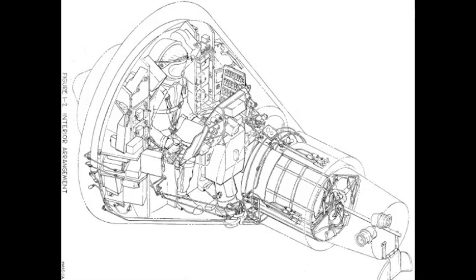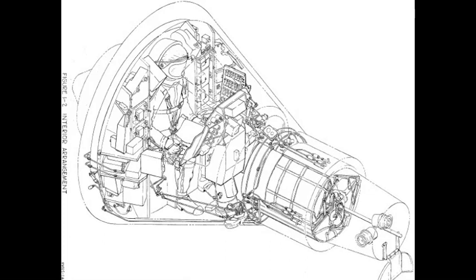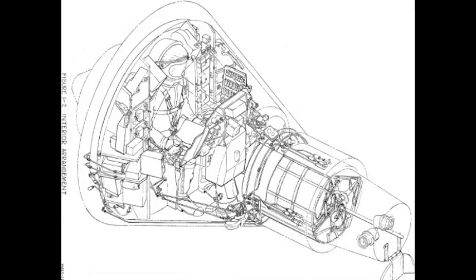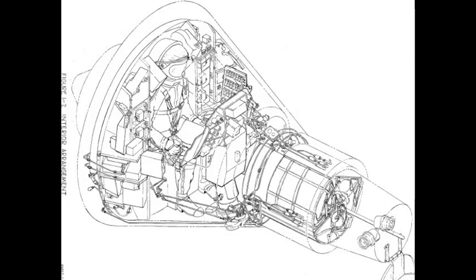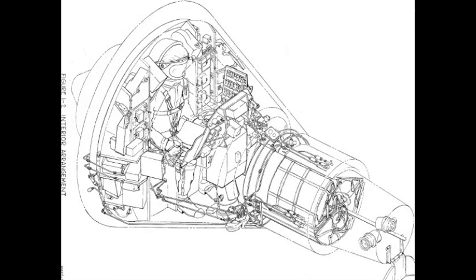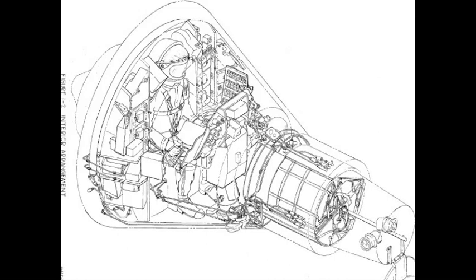The rubber cloth impact bag attached to the capsule heat shield attach ring and the heat shield is designed to absorb high-energy shock loads encountered during a capsule landing on land. During the capsule landing phase, the heat shield is released and extends the full length of the impact bag, thereby inflating the impact bag. Upon heat shield contact with land, air within the impact bag is forced out through a series of holes located in the impact bag wall, which in turn provides a cushion-like effect.